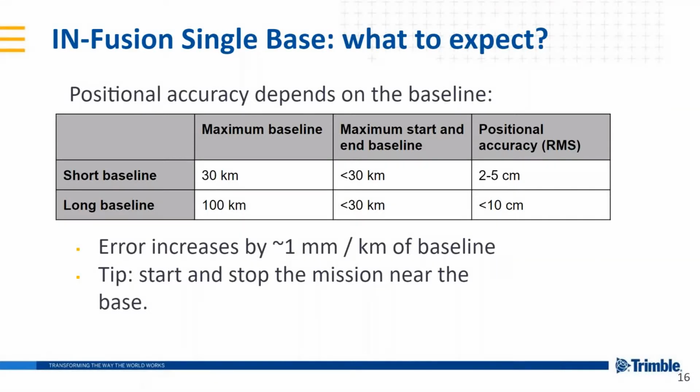The error increases by about 1 millimeter per kilometer of the baseline. As we said, try to start and stop the mission near to the base, and this will help to improve the data quality.